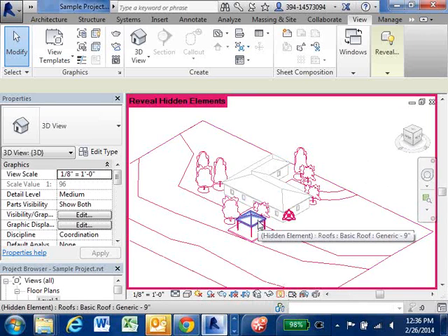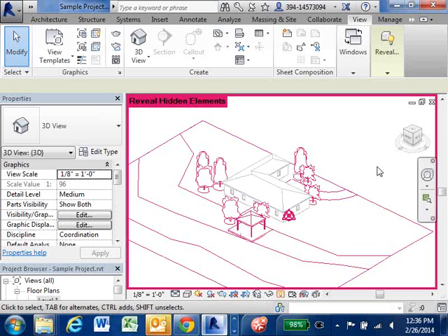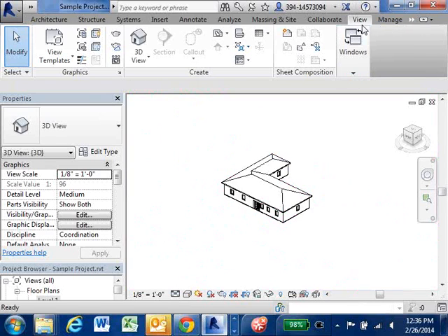One thing to note is GBXML will export even hidden items. So I would recommend deleting anything like this little shading structure for a patio. That will be carried through in GBXML, but it will not if it's turned off in DXF or DWG. So those are some things to note maybe for that. So I'll first show the GBXML.